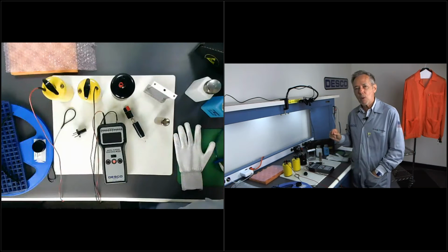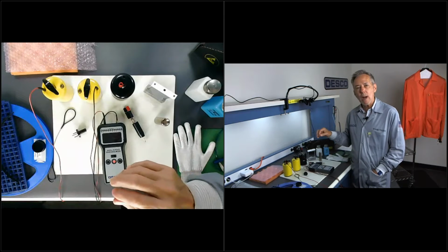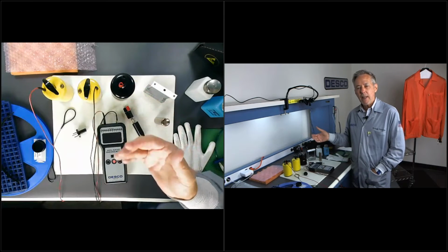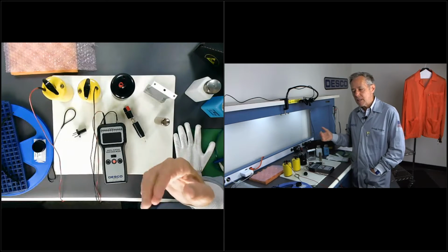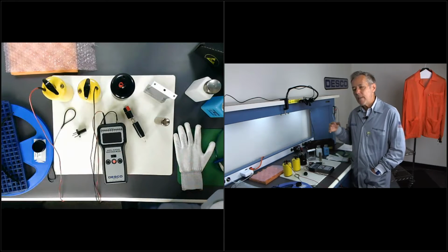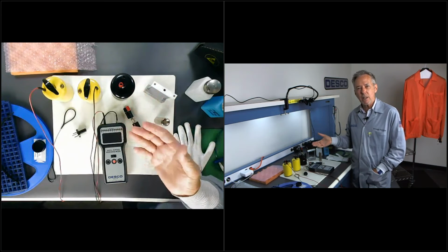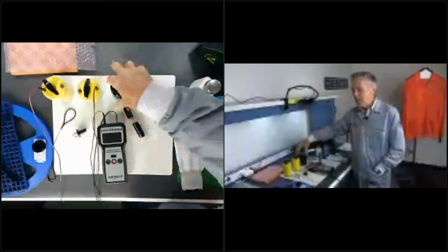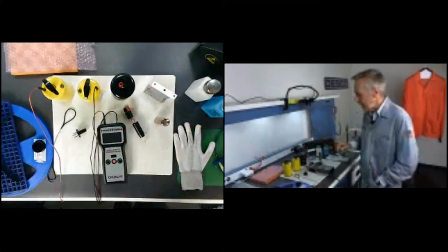I want to mention one other one before I forget. The S20.20 does not cover the requirements of packaging materials. They refer to what we call S541 for that. So if you want to know everything you need to know about testing an anti-static bag or a static shielding bag, it's S541. But using this equipment, I'm going to give you an example of some of those tests that you can make.